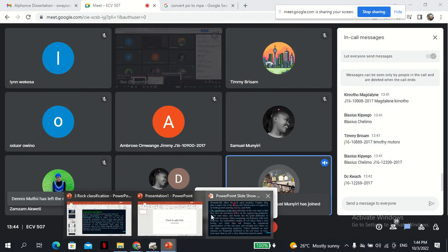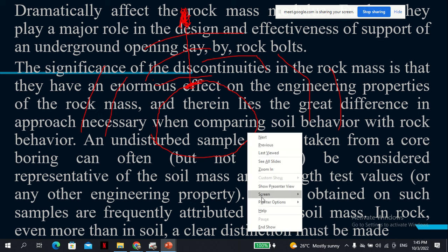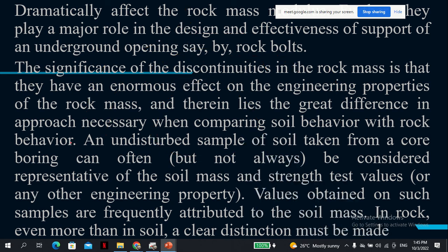to make sure, because if they are loose, if these cracks make this place loose, maybe water can flow, and you don't need that. So you need to make it stronger. So you have to apply some tensile force on the rock bolt to make sure that if the cracks are loose, it is well secured, and your tunnel is well protected. So all these affect the design of the rock bolt, like I've said.